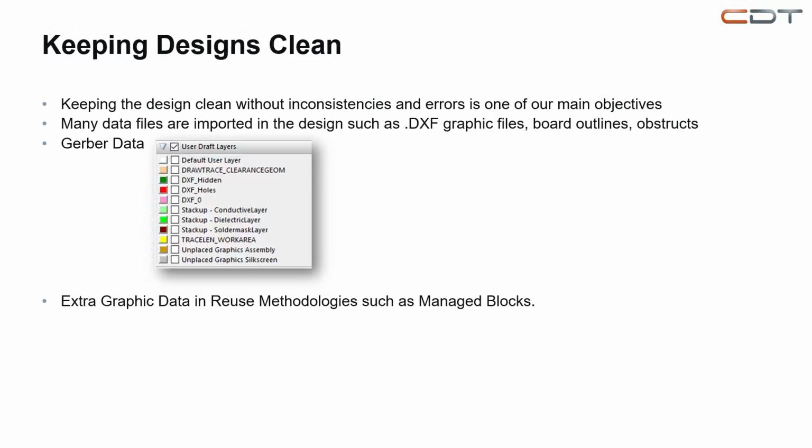This is our main objective as a designer, as an engineer, to keep your project very healthy. Remember that many data files may be imported into the design during the process, like DXF graphic files, board outlines, abstracts, Gerber data if you're using something as a reference. All these increase the volume and weight of your file, and it will be negative from a future perspective. Try to delete or clean unused objects if you really don't need them.